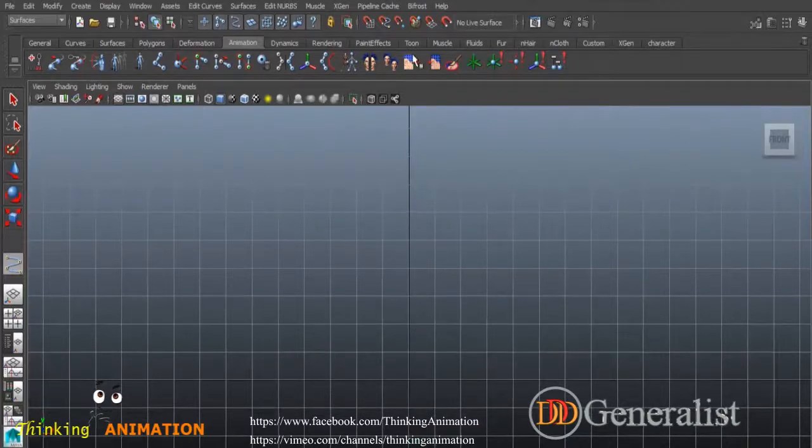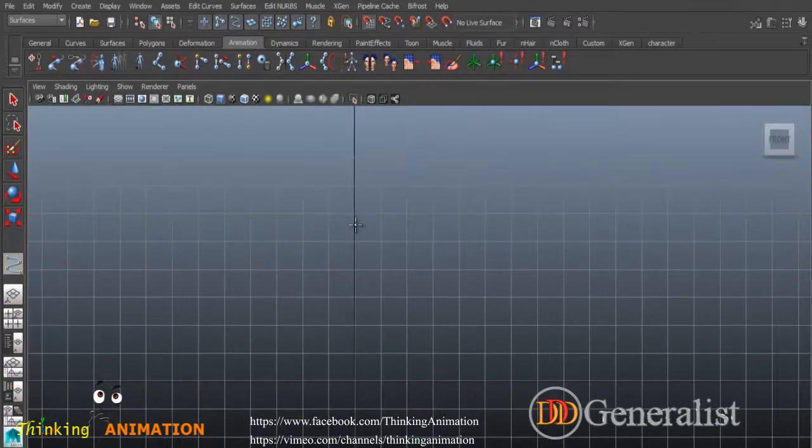So what I'm going to do here is to select turn the grid on, and keeping in focus this front line, the grid line, 1, 2, 3, and even after 3 unit, I'm going to just click start from here and keep clicking, and until I reach here, and then I'm going to turn the snap to grid off and going to start to create an arc.